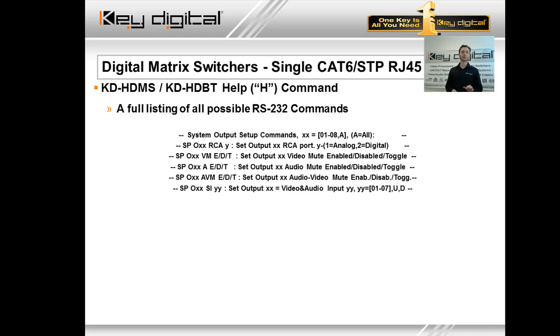Now, we're not going to spend a whole lot of time on this, a whole lot of detail, because we are going to go into more detail on that on level 3, okay, where we're going to do some of the advanced switching options there. But I will have you know that the SPO XX SIYY is the most generic of all the switching commands, the one that is most commonly used, because this assumes that your output XX, whether it be the card slot or the output number again, varying on Hercules or Digital IQ, when it selects your input YY, it's going to select the audio and the video from the HDMI port on YY, okay? So that's your generic switching command.